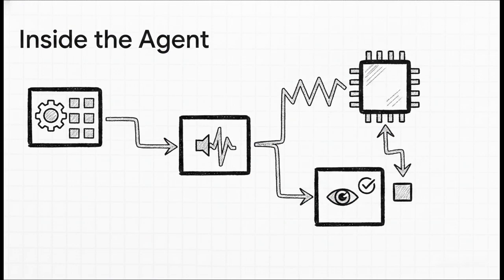Well, it's got three primary subcomponents. First up is the sequencer. This generates and controls the stimulus sequences and then hands them off to the driver. Now, the driver's job is absolutely critical. It receives these high-level transactions and converts them down into the gritty, physical, signal-level activity that the design under test, or the DUT, can actually understand.